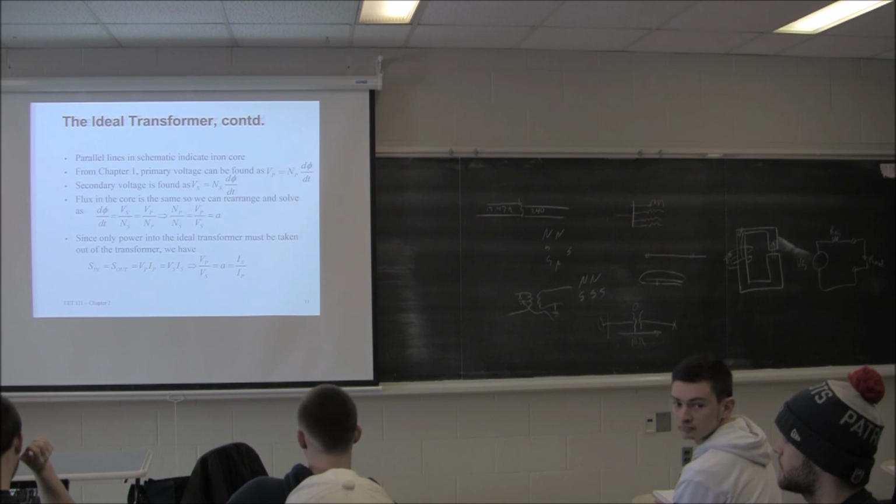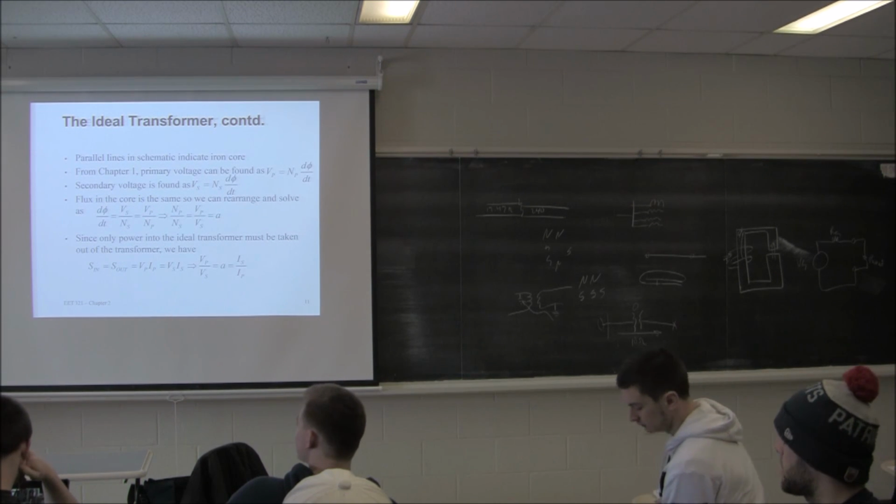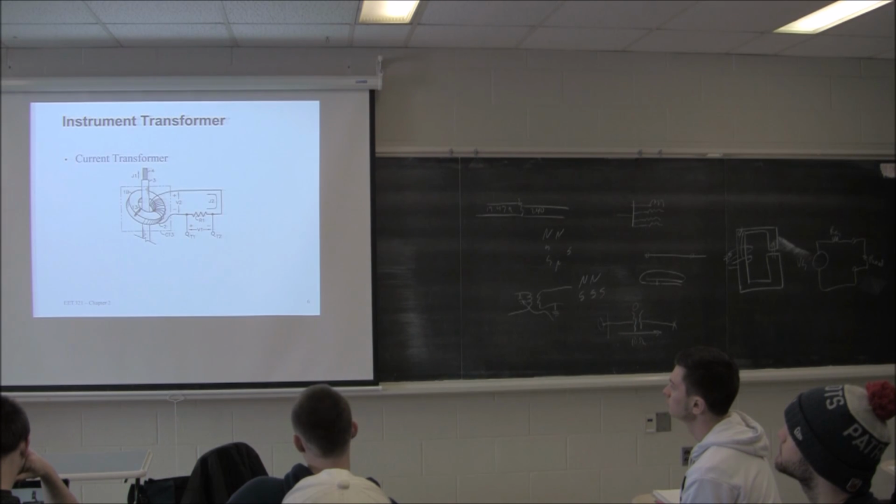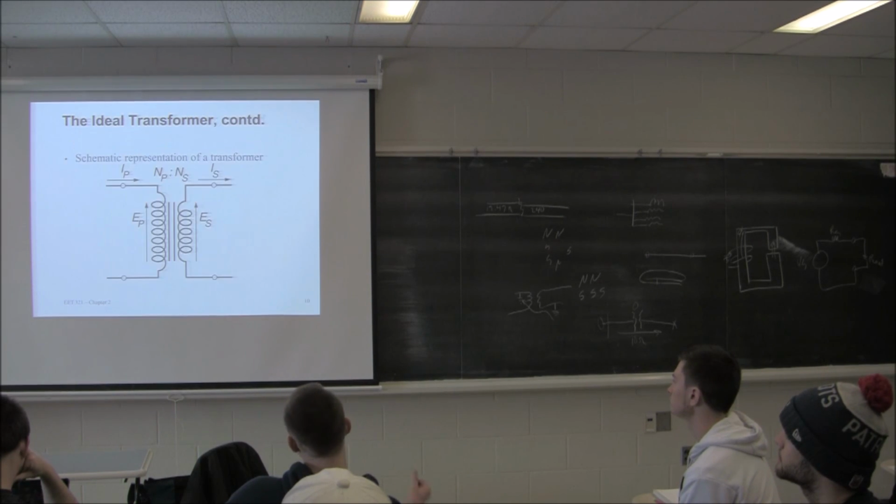Yes, sir? So would that change from a power transformer to a current transformer? Nope. Same exact thing, because the current transformer is a power transformer. This is just a turn of 1 on the primary side. So it's exactly the same.